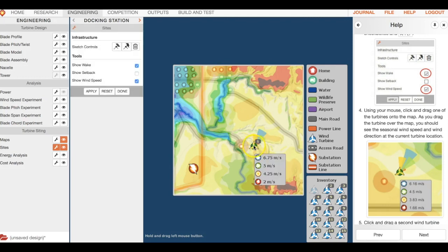And we can see, it doesn't say it here, but since you're working with me, show setback. That's going to show you the area. See, this is showing me I'm too close to this house. So I need to come back over here a little bit, and so they're not touching. Okay, so that's an important piece to have there too.